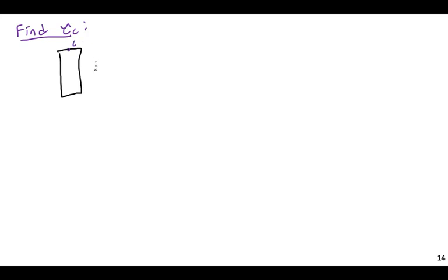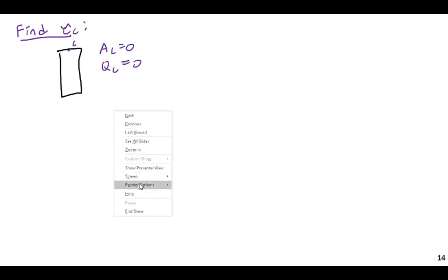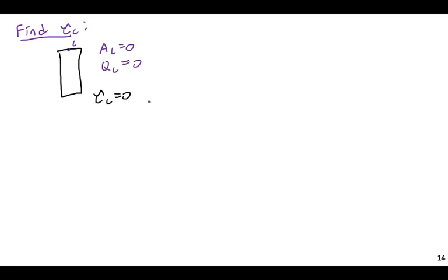There's no area here. There is no area above C. So therefore, area at C equals 0. Therefore, QC is 0. And therefore, since we are using the equation tau equals VQ over IT, if Q is in the numerator, then by very simple mathematics, tau C must be 0 ksi. Fairly straightforward. All right. So we have those stresses at those 3 points.